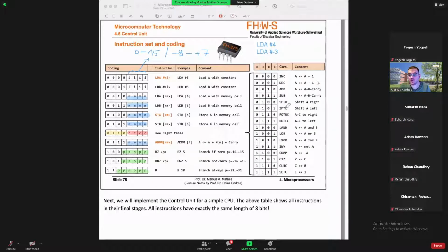So for example, if I want to execute a XOR, A XOR B, then this is encoded with 1, 0, 1, 0. This bit pattern has been added here. So XOR is encoded with 8 bits. An add is also encoded with 8 bits: 0, 1, 1, 0, 0, 0, 1, 0. So the logic and arithmetic operations, all of them need 8 bits for encoding.